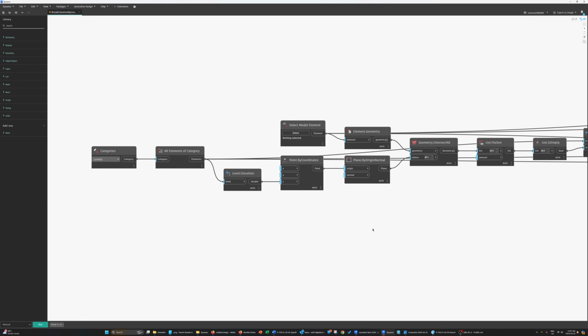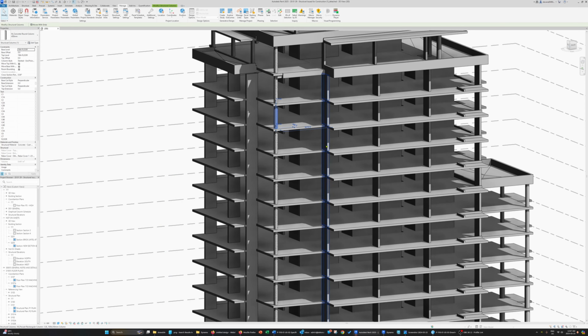And I do have a major script for formwork because ultimately what we see here, I can analyze each geometry, each face, and extract the area values of each one of them based on the type of component they are. For example, a slab needs to be formed on the sides and at the bottom, it doesn't need the top part. A column only needs the sides. It doesn't need the bottom part, doesn't need the top part. A wall is going to be the same. So with all of these things in perspective, we can actually create a script that's going to get us to 90% accuracy in terms of formwork.